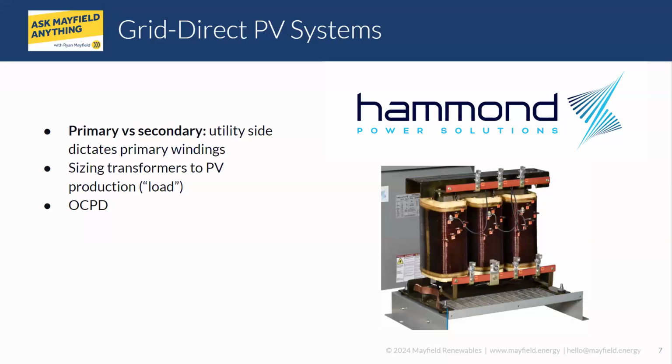Sure. Some of these are points that are often confused in the topic of transformers. So just a couple of things from a basic standpoint to get started. Primary and secondary, those terms really have to do with the way the transformer is designed, based on some of the unique characteristics of a transformer. A transformer has to basically flux up when it's initially powered up. So as a company designing transformers, the primary side is the side that the energy is flowing from, or into rather.